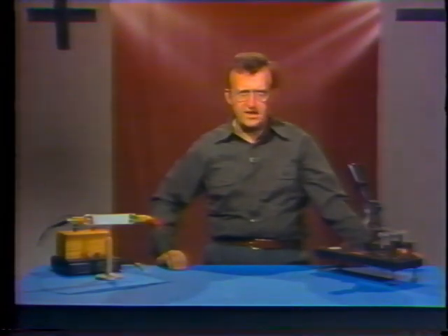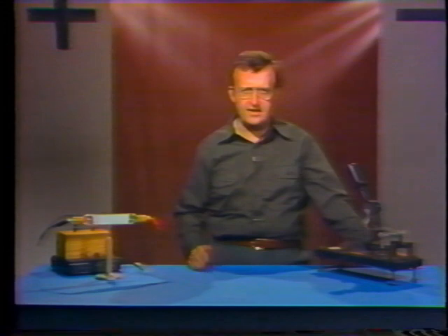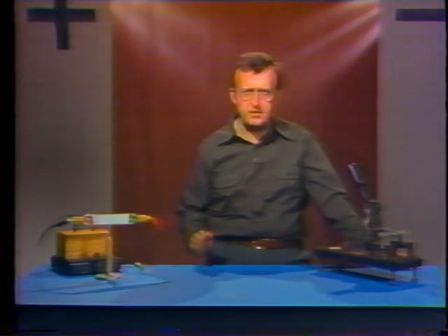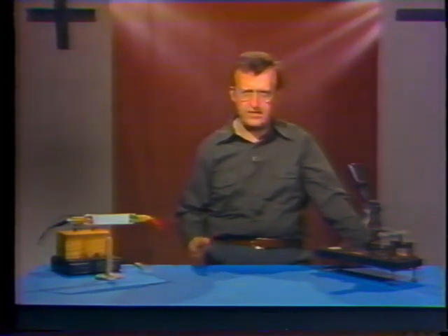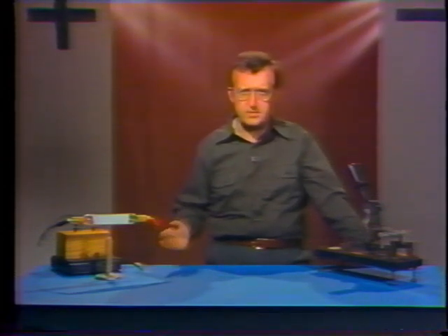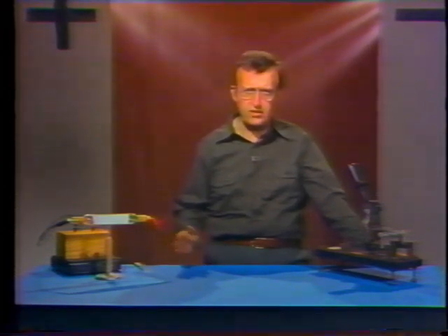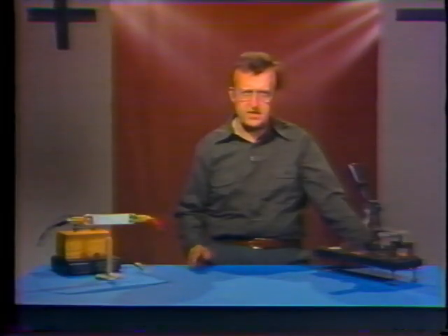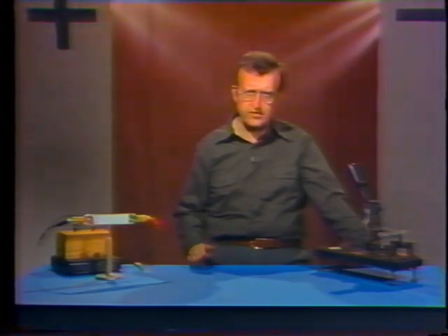Like a fuse, a circuit breaker is an electrical protective device that can open a circuit to interrupt current flow. As we saw in the last segment, a fuse element melts to open a circuit when excessive current flows through it. The equipment in the circuit is thus protected from the effects of too much current. But the fuse is damaged and it must be replaced. You can't just reset a blown fuse and use it again. A circuit breaker, however, can be reset after it has opened a circuit. That's one advantage circuit breakers have over fuses.